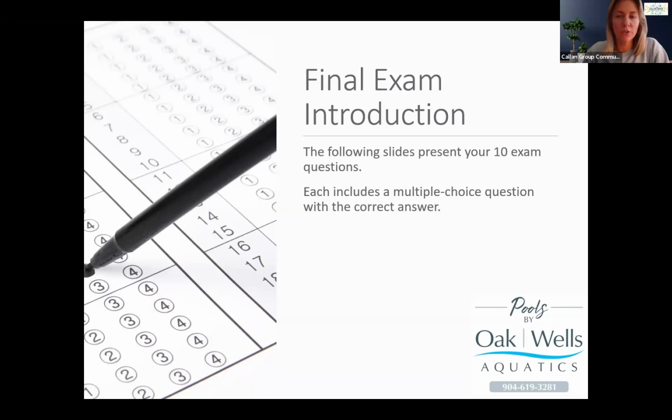There's a question. Autofill pumps fail, do not last for long periods, correct? So there's not an autofill pump typically. The pressure for the autofill is just the water pressure for the water supply on the property. So it could be like a hose bib. They do fail semi-regularly. It depends on which type of autofill you have.